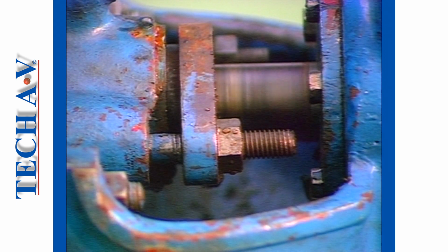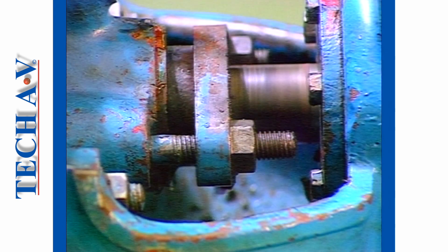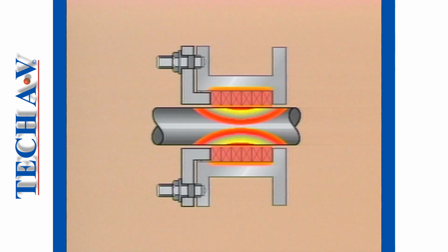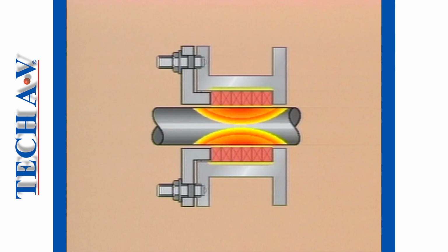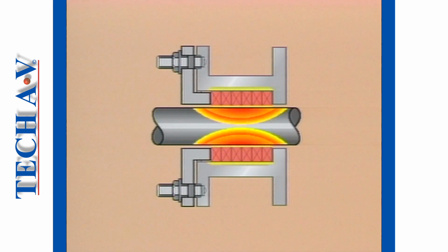But let's first go back a moment to packings. As you recall, packings are dependent on a flow of product or liquid at the interface of the shaft or sleeve. When wear occurs, the leakage past the packings increases. And if the packings are even slightly overcompressed, then the liquid barrier can be destroyed, resulting in overheating and shaft or sleeve damage. This means constant attention and increased chance of error.